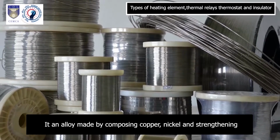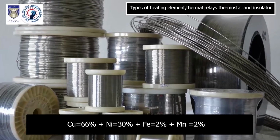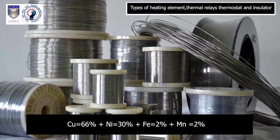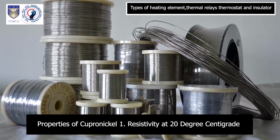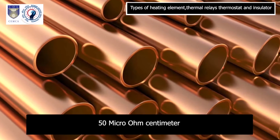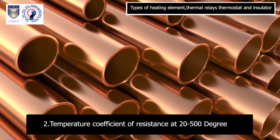It is an alloy made by composing copper, nickel and strengthening elements such as iron and manganese. Cu is equal to 66% plus Ni is equal to 30% plus Fe is equal to 2% plus Mn is equal to 2%. Properties of cupronickel. 1. Resistivity at 20 degrees centigrade 50 microohm centimeter. 2. Temperature coefficient of resistance at 20 to 500 degree centigrade